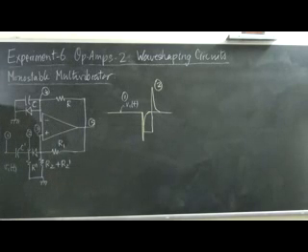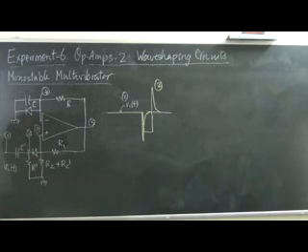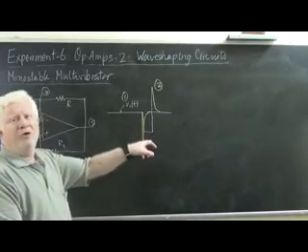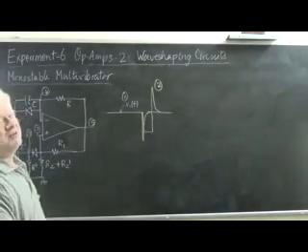The next thing to observe is that there is a diode facing towards the left. This diode simply acts as a clipper and rejects positive parts of the waveform number 2 to leave it only with negative parts. So what you get next is only the negative impulses of the differentiator output with the positive impulses removed.